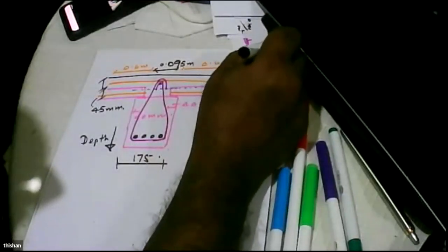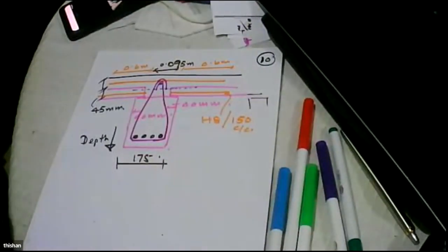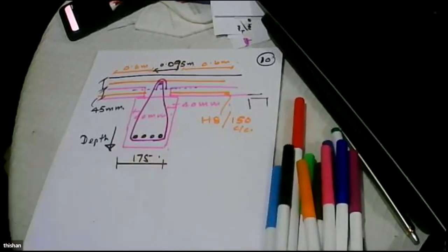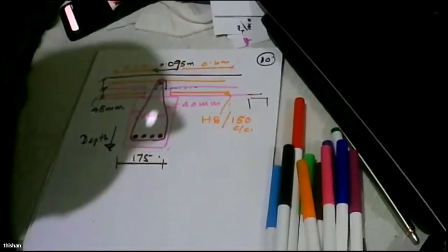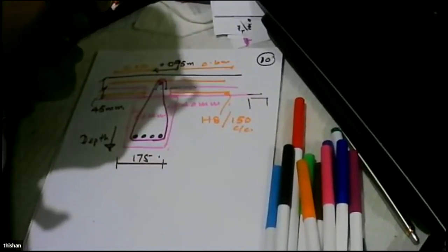So generally when you have a 90 millimeter slab over 2 meters, shear will be minute. You don't have to worry about shear. Is that clear? Yes, sir. Then shall we take the questions? Yes, sir.